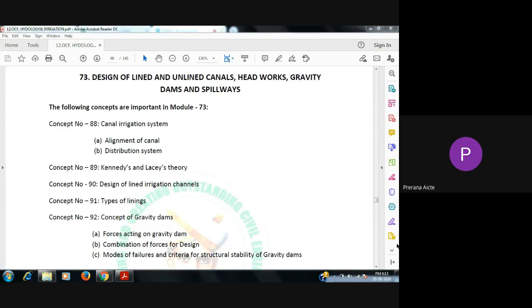So a hydrograph is a relationship between the discharge and time. Then a unit hydrograph is a direct runoff hydrograph resulting from 1 centimeter of effective rainfall. For example, take a direct runoff hydrograph resulting from 5 centimeters of effective rainfall, where an ordinate of the direct runoff hydrograph is, for example, 100 meters cubed per second. For 1 centimeter, it is 100 by 5. This is the ordinate of the unit hydrograph.